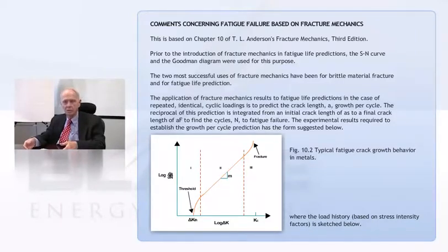And that's an area where you hear it said that this is a place where fracture mechanics should shine. And it does okay. I'm not saying that it doesn't, but the notion is that in fatigue, if you think about bending a bar back and forth until it breaks, in the course of cycling, you get intense strain hardening at the tip. And a strain hardened material looks a little more like a brittle material than a ductile material.